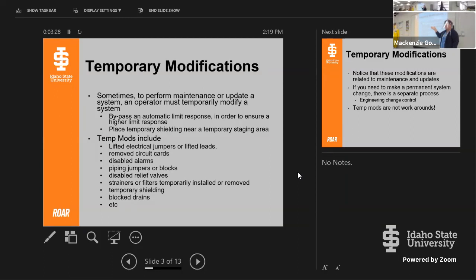That power corresponds to a temperature that the reactor will be at when the fuel is producing that much power, right? Because we talked about in materials class, one of our major assumptions at all times is we will not melt the fuel cladding, right? That's kind of an ironclad operating principle. Whatever we do, we will not melt the fuel cladding.